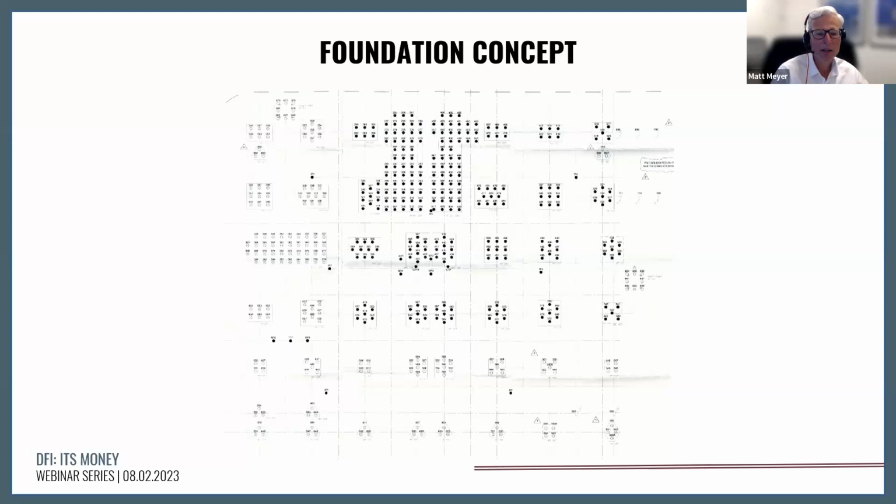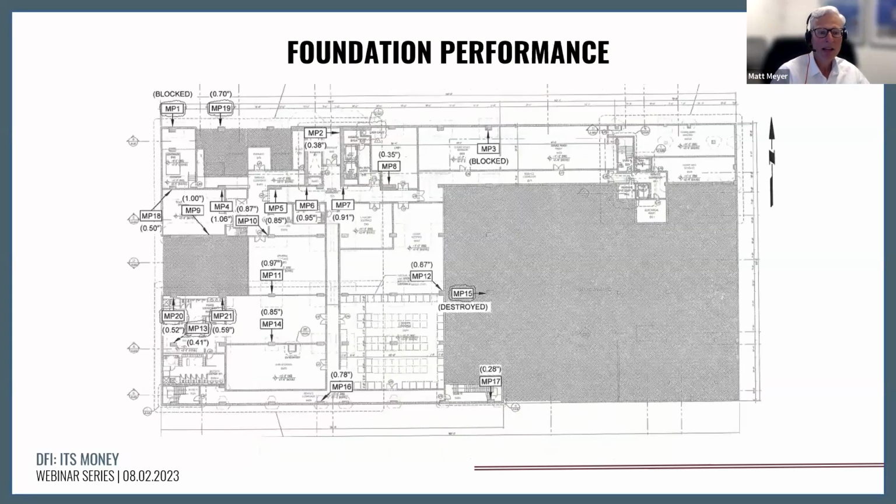The piles shown in dark in black there with the colored in circles, those particular piles are our long foundation elements that extend to elevation minus 85. And within that zone of the tower, that stratum 7A was consistently present. So we had to bypass that weak compressible subsurface material to attain settlement compatibility between the medium length piles and the long piles. And indeed, we did obtain settlement compatibility.